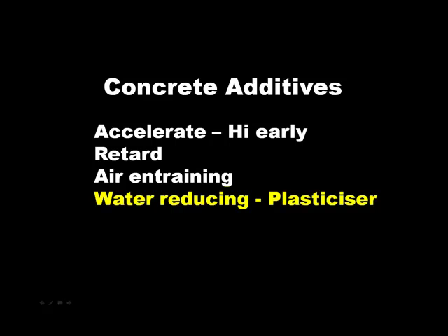And in my experience, typically in a precast concrete yard, they have a rebar that's closely spaced, and there are post-tensioning conduits, or there could be post-tensioning strand. It's a very dense matrix of material inside the forms, and you need to ensure that the concrete moves around these rebars and fills every possible void.